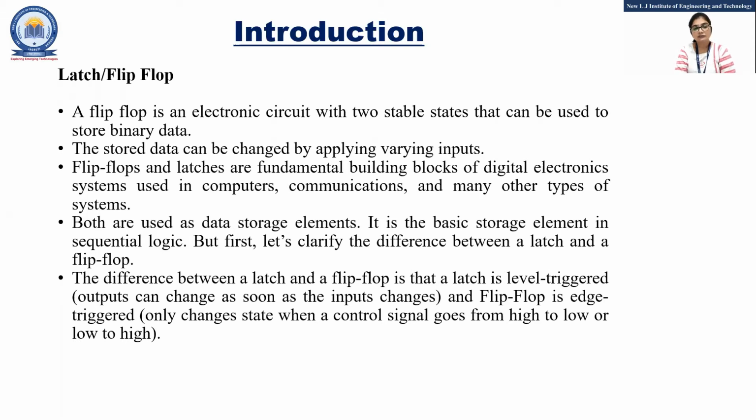Now we will see the difference between latch and flip-flop. The latch is level triggered, means outputs can change as soon as the input changes. It is a transparent device. And flip-flop is an edge-triggered device, means it only changes the state when the control signal goes from high to low or low to high level, as we have already discussed in the previous lecture. The flip-flop is an edge-triggered device and the latch is a level-triggered device.